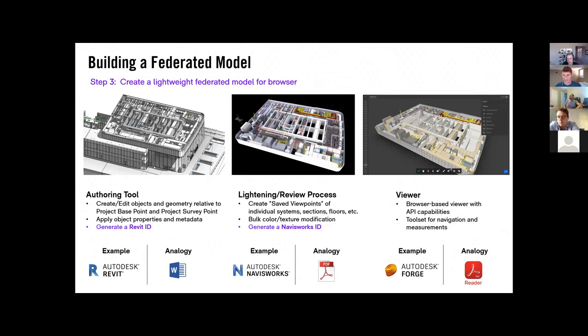The answer lies in this important purple text here, these IDs. If you have an object in the 3D model, like a pump, it will forever know that it has this Revit ID all the way back to my authoring tool. If I need to move that object in space, maybe I'm doing a tenant fit out, moving walls and relocating assets, I can move an object and maintain its ID, and I won't lose track of all these connections I'm making, all these modifications I'm applying to get that into my digital twin.